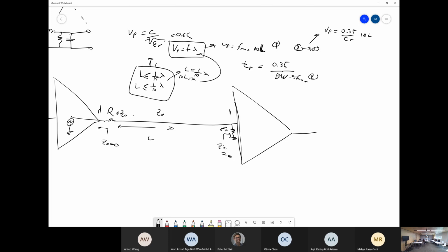You can choose. I think Torsten says 10. I like to use 15 because I'm scared. You want the length of your transmission line, or trace, or PCB track, or cable, or twisted pair to be generally less than 1 on 15 or 1 on 10, and then you have to worry about absolutely none of this. It's only when it starts getting really large that you have to start worrying about impedance matching.